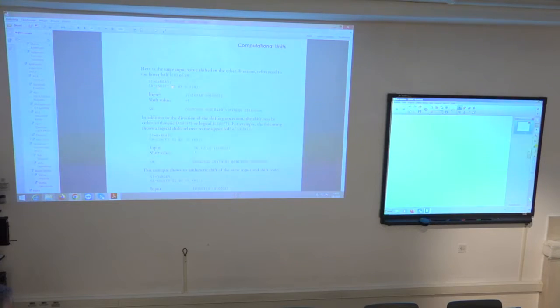No, this is a logical shift of shifter input by 5 positions relatively low. So it takes this value from the input register, places it over the lower output word, and then shifts by 5, meaning 5 positions to the left.